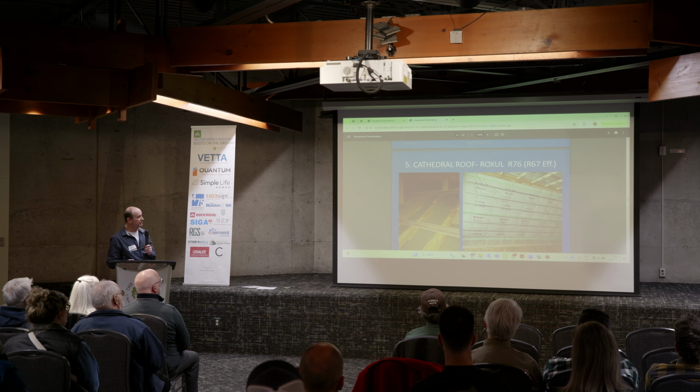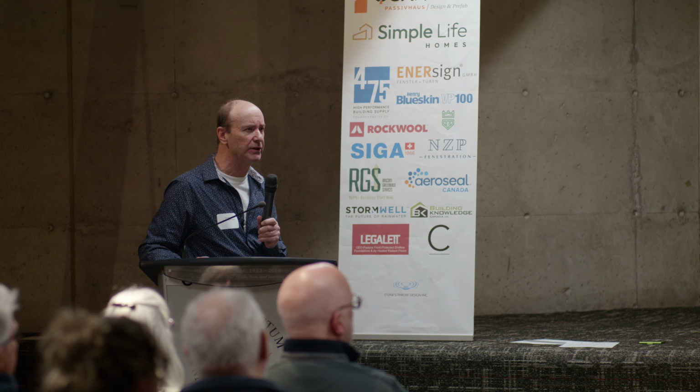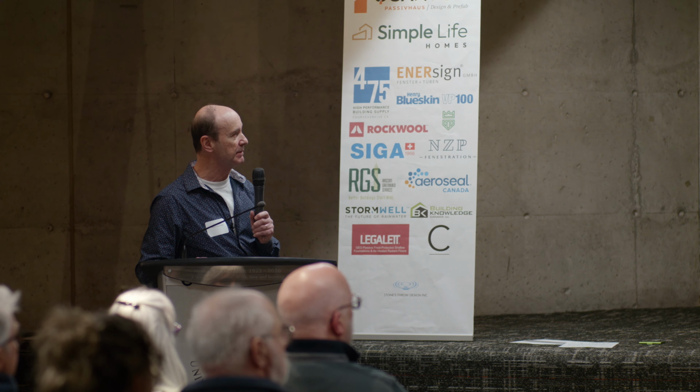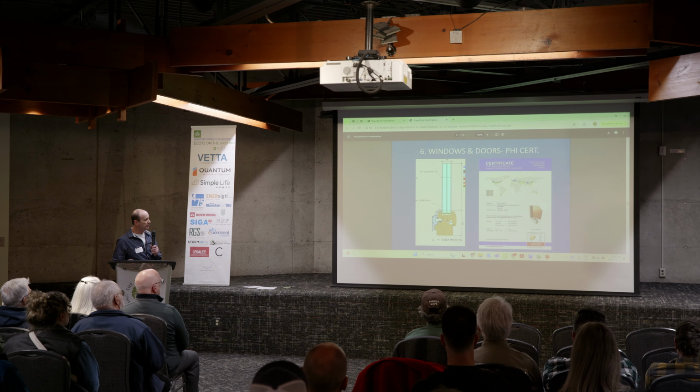Part of the assembly was an unvented assembly with a cathedral ceiling. And this is the interior that you're looking at here with the air control. I can't remember if this was the main air barrier in this roof assembly. I think it was. This was the air and vapor control area in that particular part of the assembly. This is the back side of it. It actually did connect with the main attic space, so there was a pretty good amount of venting available.